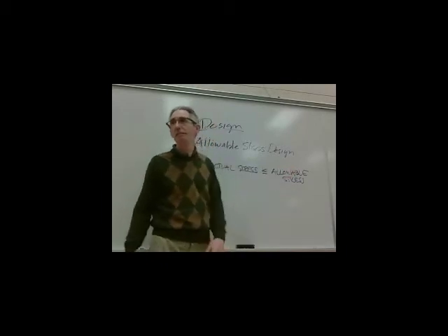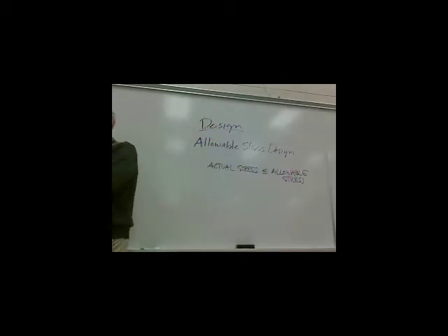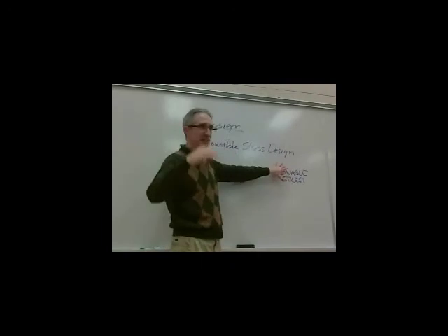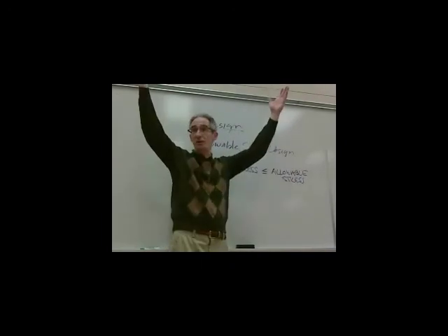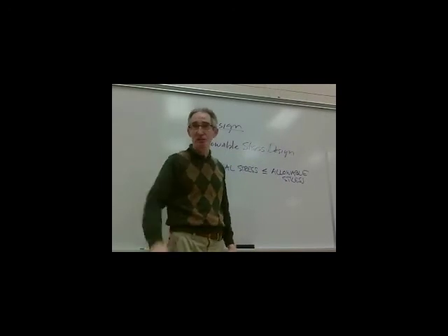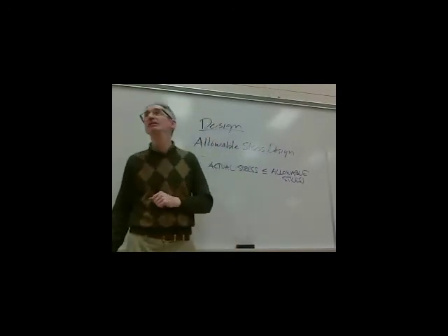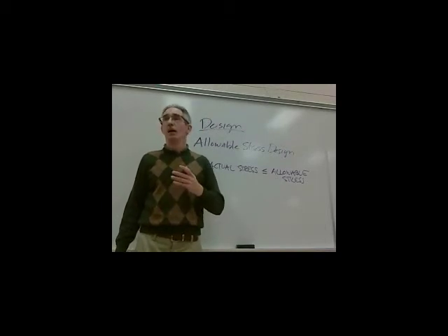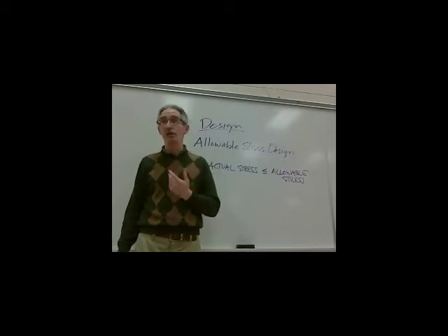Yes. Now, for specific materials, do they generally set the allowable stress at a certain percentage of the stress that that material will take? Yeah, what he asks is, will they set this at some percentage of the maximum or the ultimate? The answer is yeah, they will. Some of that's judgment. It's not like they say for steel, we're going to put it at 80% of whatever the maximum would be. It's generally across the board. Yeah, in the old steel specifications, they did that.